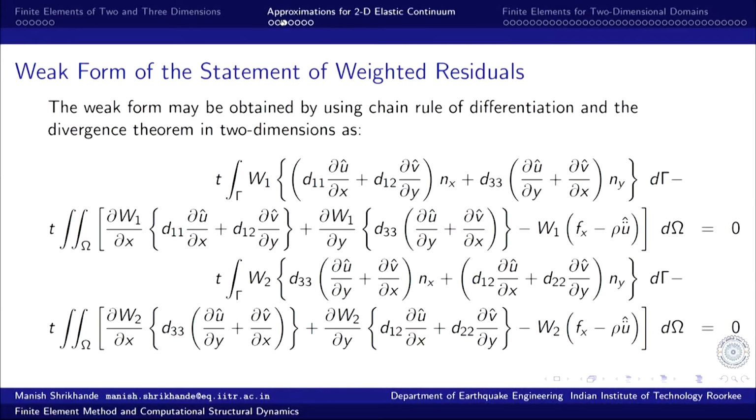We will also, in this particular case, because the loading conditions are constant and not changing with time, find that the inertia terms are not significant, and we will drop these acceleration terms. So, W1 integral of W times rho u double dot. This is the acceleration term.